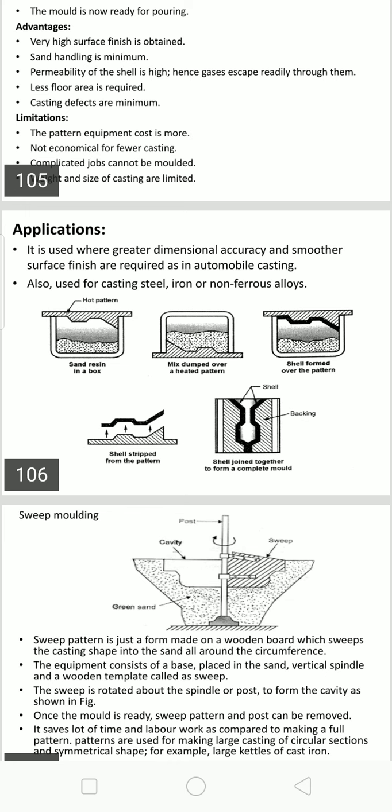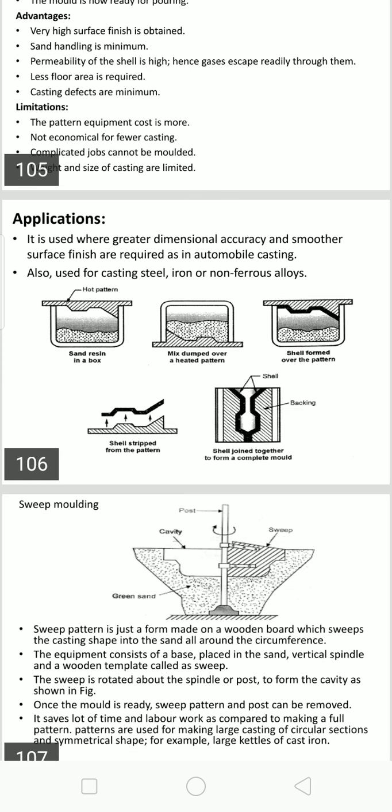The next step is assembling and keeping in the mold box. Another shell is prepared in a similar way, and both hollows are assembled together either by adhesives, by clamps, or by spring clip. Then this is placed in a mold box as shown in the last figure and surrounded with surplus material like wire sand, metal shards, gravel, waste sand thrown here and there on the foundry floor. You have to pack it around the shells. Now it is ready for pouring.